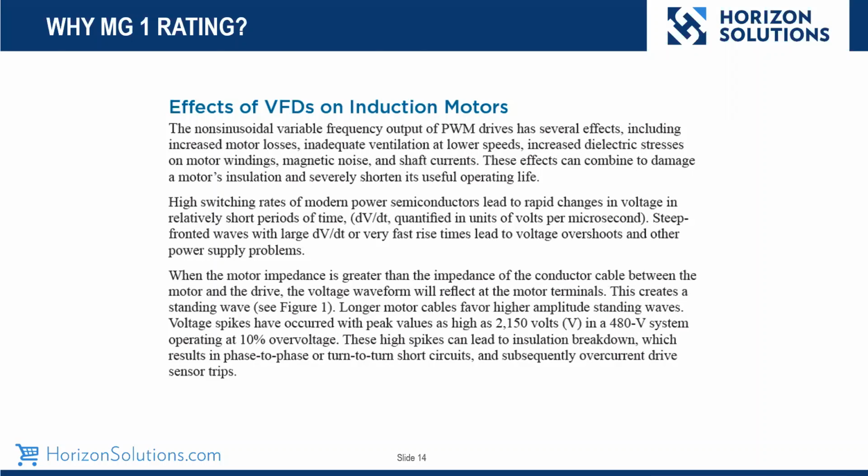Also, things to consider with these short switch times were the longer motor cable lengths. And sometimes with these extreme motor cable lengths, you're talking out over 1,000 feet, you would see voltages go periodically as high as 2150 volts.